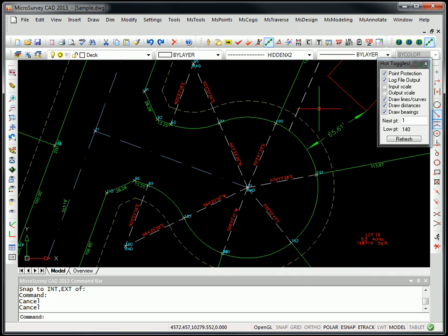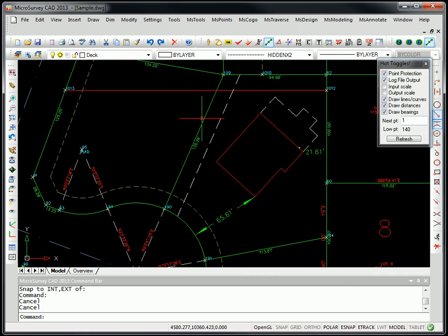Now some of you might have said, well, I could have just offset this line here, and you could do that, but what it'll do is it'll offset that line but also use the same color and layer of the line you offsetted, whereas this lets you draw a new line on a specific layer, and you can quickly make it parallel to another line and just use those new snap or grip modes to extend it or shorten it and snap to specific lines to trim it.